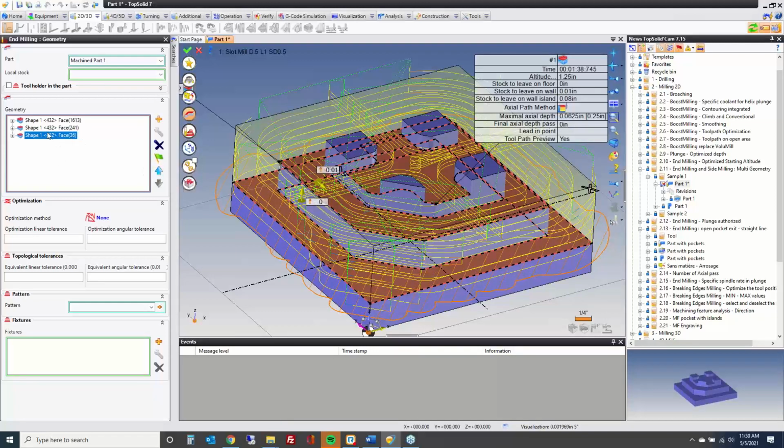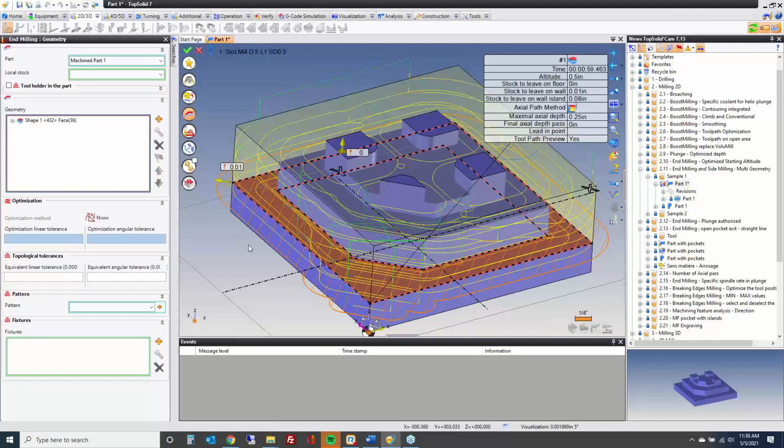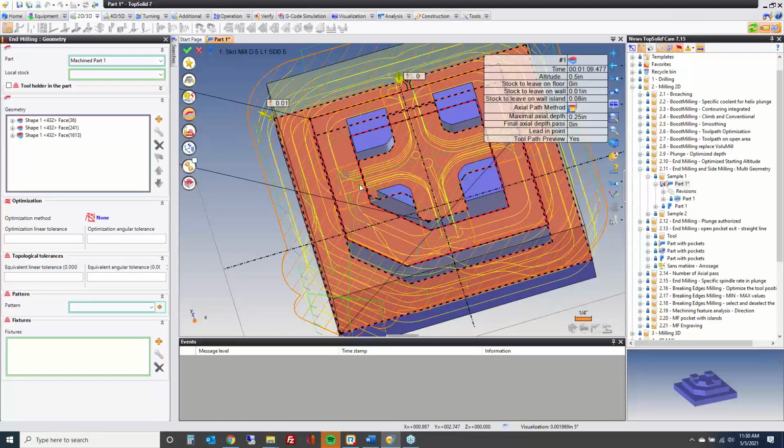To make it easier, I want to machine this face first, then this face, then this face. And you can see it's optimizing accordingly. So if you order them or you go from the bottom widest feature first, then to the next one, then to the next one, it of course is paying attention to the stock. Is that what you guys were looking for?